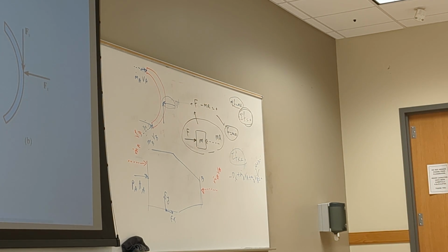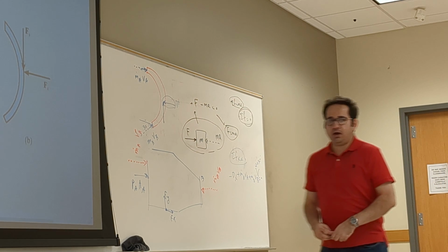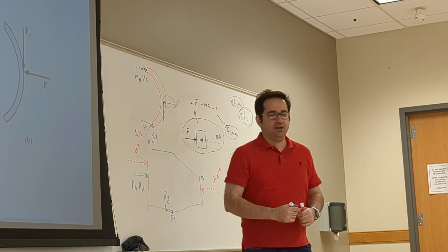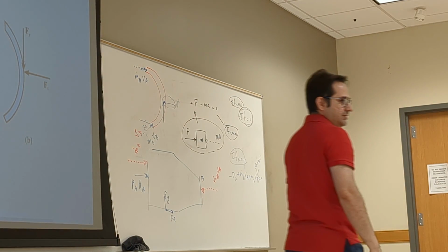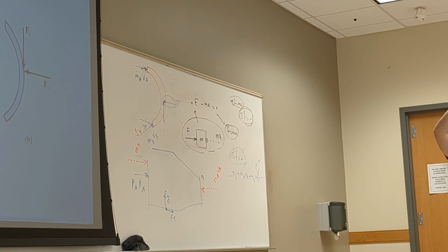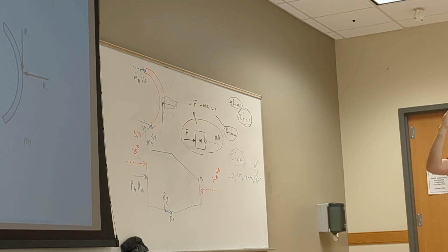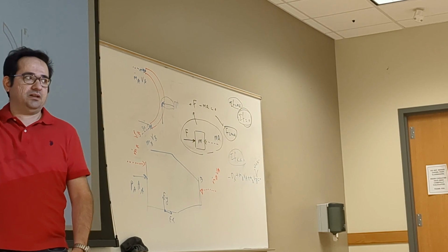Professor, now looking at it and thinking about it, the m dot, since that's rho V A, for B, would you use the area from before? So why do you use the area from before now? Let's talk about that. Don't take anything for granted. If you write the Bernoulli equation about this point, what do you get? That the velocities are the same. Yeah, let's forget about the height, so delta H is zero. Forget about the pressure because both of them are P0. So velocity here is equal to velocity there.